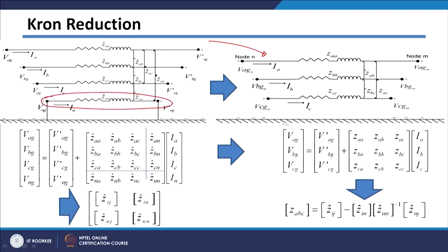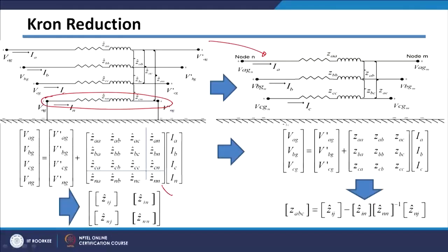But it is not just directly eliminated. We have taken the effect of those conductor currents on the phase conductor by doing Kron reduction. And using the Kron reduction, we have seen that your 4 by 4 primitive impedance matrix, so this was your primitive impedance matrix, which is basically conductor size by conductor size. In this case it is 4 by 4 because we are considering 4 conductors here.